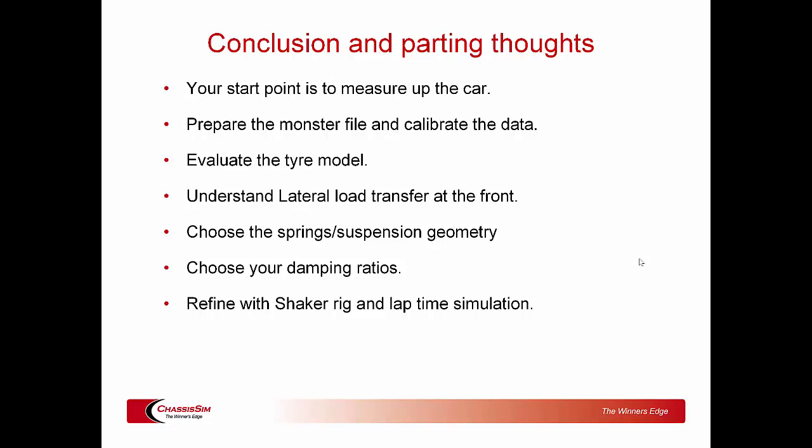You then evaluate the tire model. You understand your lateral load transfer at the front to generate the mechanical, your grip balance equation. You select your springs and geometry to get your tire heating. You choose your damping ratios. That's when you work in with refining with the shaker rig and lap time simulation. But just remember, ladies and gentlemen, our 2 jobs as a race engineer are grip and balance.